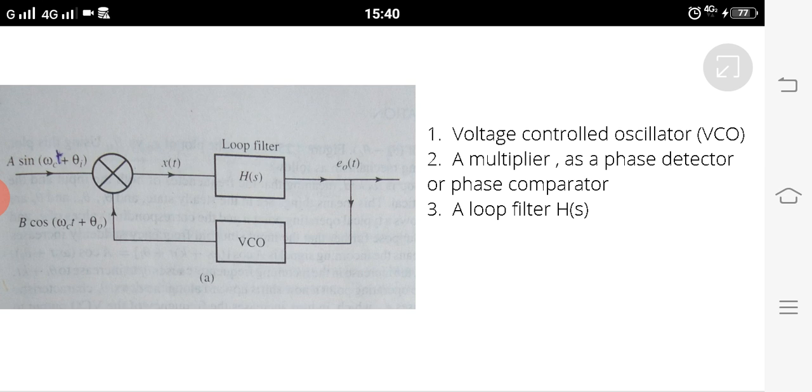Now a PLL operates on a similar principle, except that the quantity fed back and compared is not the amplitude but the phase. The VCO adjusts its own frequency until it is equal to that of the input sinusoid. Now the frequency and the phase of the two signals are in synchronism, or we may say they are synchronous, except for a possible constant phase difference. This is the condition that we are considering at this moment.